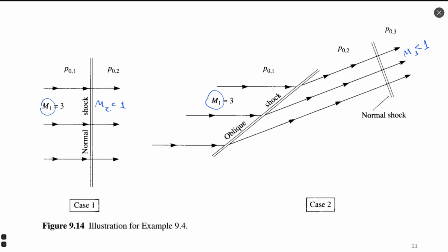Okay, here it is, I found. We have Mach 3, and we can find the corresponding ratio of stagnation pressure according to appendix B, P02 divided by P01, a ratio of stagnation pressure as a criterion of efficiency of the flow, which would be approximately 0.33.